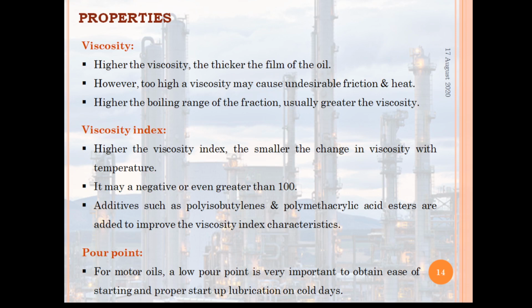Next, the pour point. For motor oils, a lower pour point is very important to obtain ease of starting and proper startup lubrication on cold days.